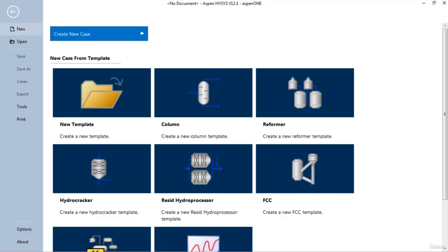Task 1. Specify the assay management information. The Aspen HYSYS assay management feature greatly simplifies the specification of properties environment inputs when it is used. In this portion, you will see firsthand how once the assay management option is invoked, HYSYS will load a suitable component list and create a fluid package.